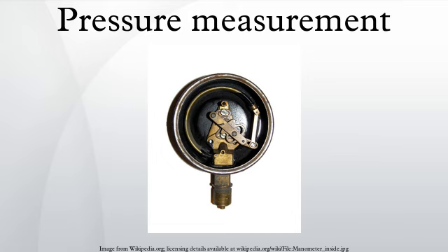PTC 19.2 provides instructions and guidance for the accurate determination of pressure values in support of the ASME performance test codes. The choice of method, instruments, required calculations, and corrections to be applied depends on the purpose of the measurement, the allowable uncertainty, and the characteristics of the equipment being tested.